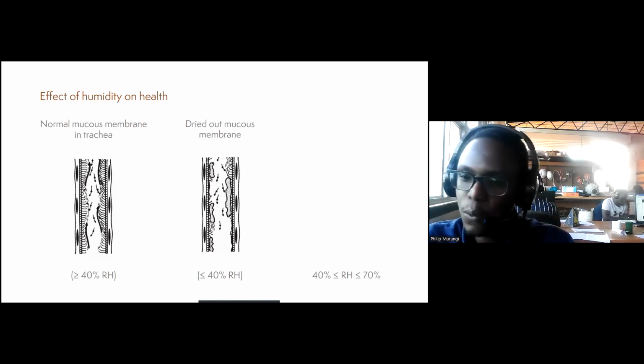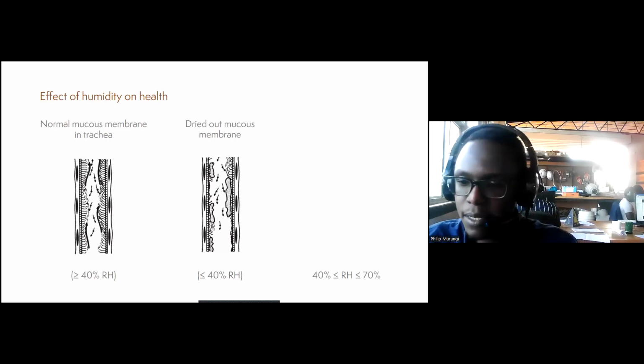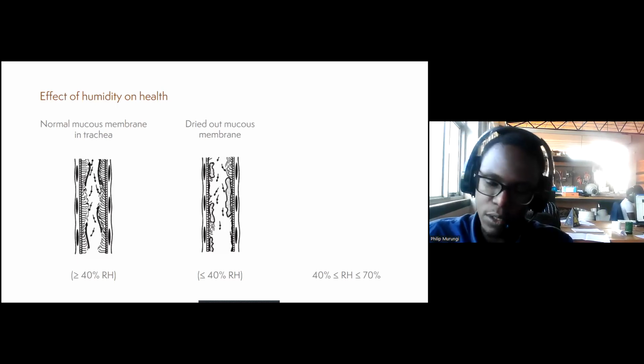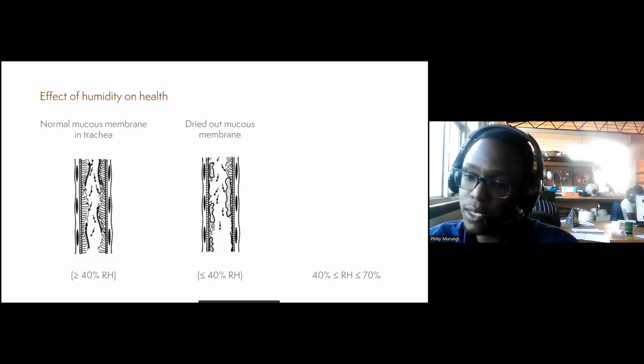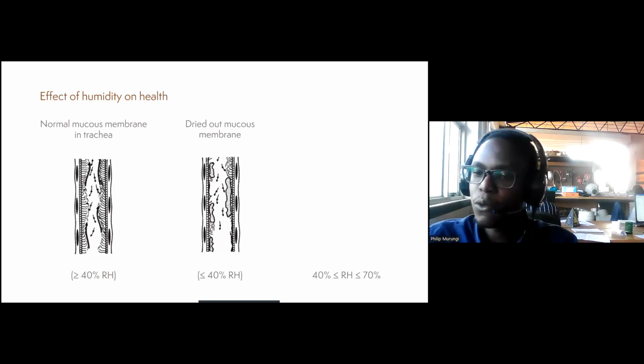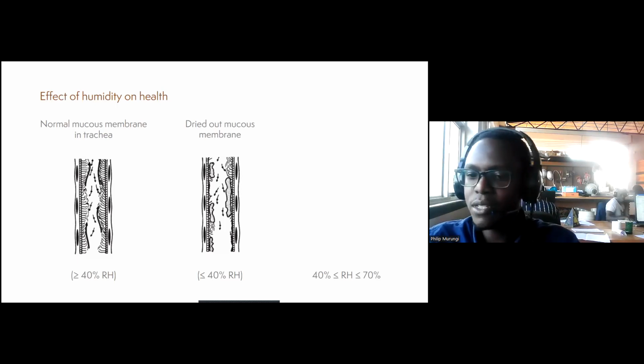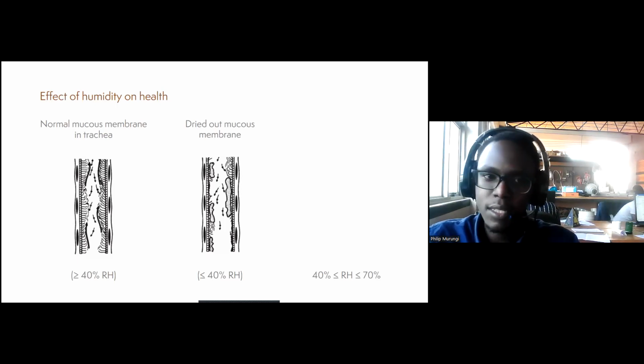So what you basically want is a humidity that's between 40 and 70%. This kind of humidity in the room reduces the fine dust content in the air. It activates the protection mechanisms of the skin against microbes. It reduces the life of many bacteria and viruses, and it reduces the odor and the static charge on the surfaces of objects in the room.